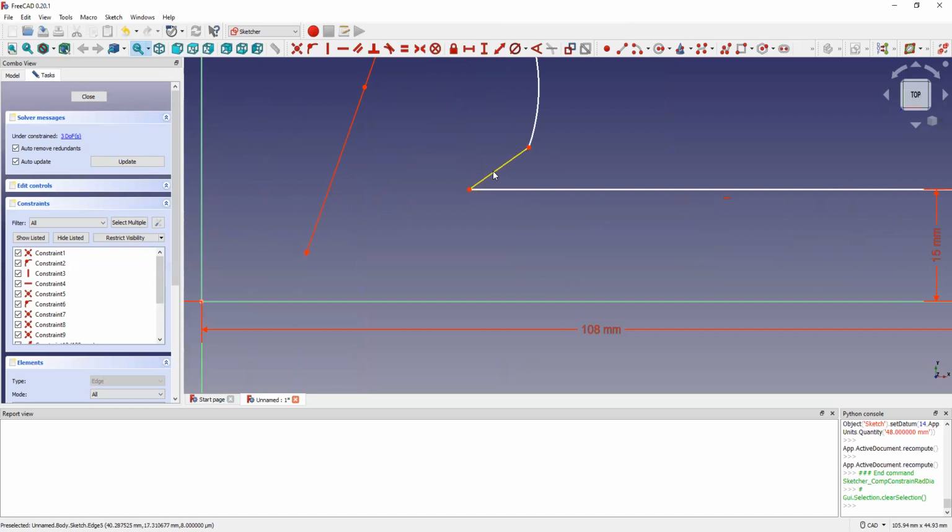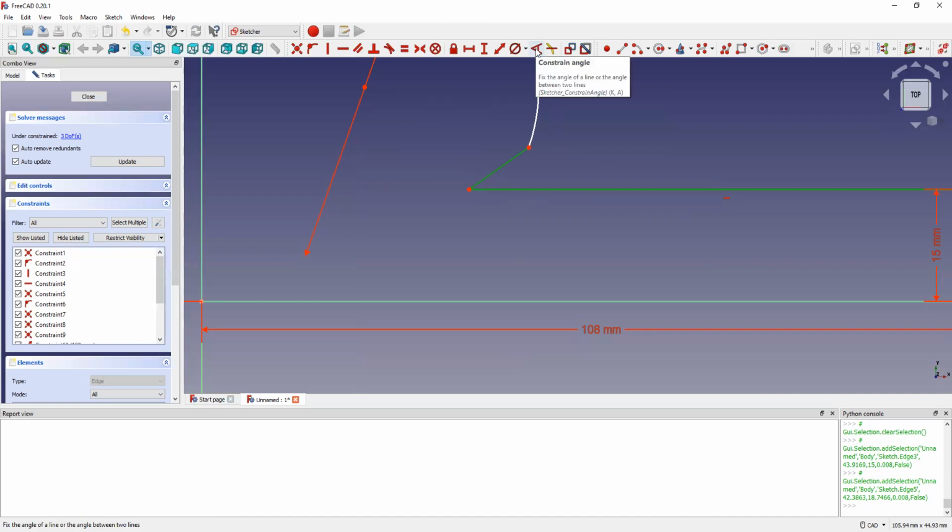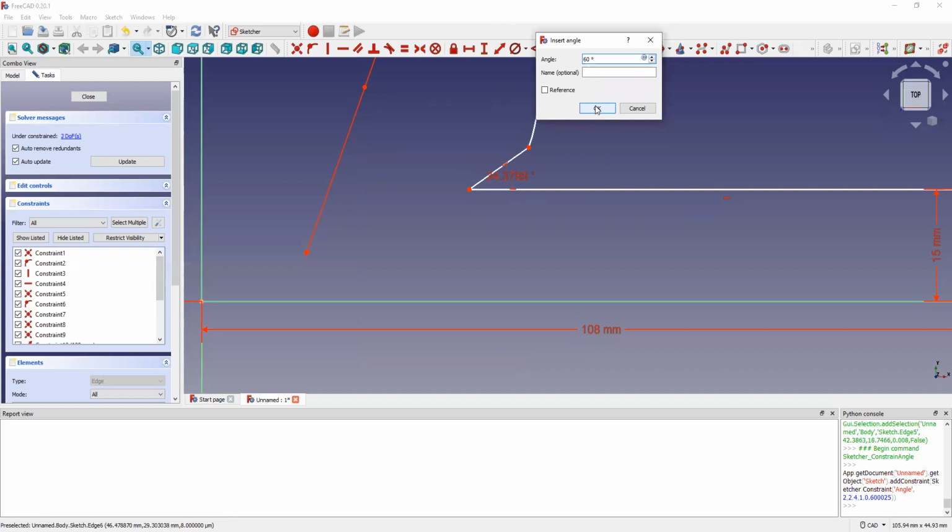Then there's a mess up here. When you see such a thing happening, it means this part and this one should be at a right angle with each other. It should make an orthogonal interface. This one is already aligned horizontally, it's fine, right? So you click this plane and this plane, then you can insert any angle you want in between them. But in this case, it's 90. If let us assume it was 60, you come and click this one and put 60. You see?